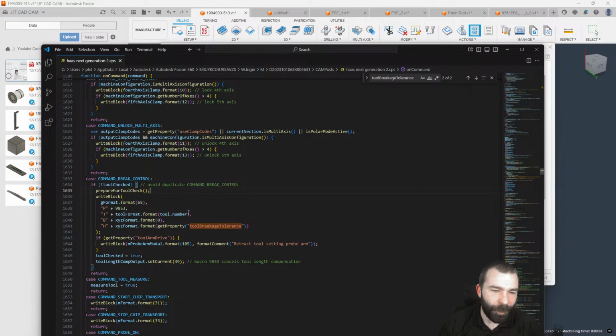Basically, what I'm looking for is the actual code that's going to get dumped out of Fusion in order to write that cycle for break control. What I would recommend, who was it that asked that question? Ash Designs. If you're looking to broaden this to do it after X amount of M30 cycles or something of that nature, you 100% can come in and program that up. Now, again, depending on your tool or your machine that you're using, you can actually go in and set group tooling that will auto swap those tools out when they discover if they're bad or not, as well as based on linear footage for wear type settings, right?